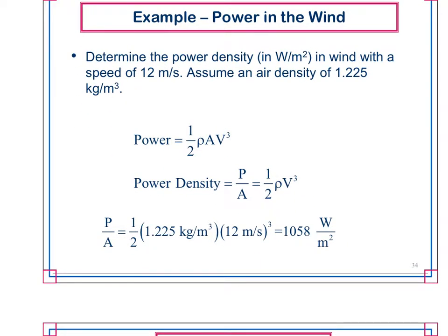So let's take a look at what the question. Does changing the number of blades on a turbine, it seems like it wouldn't change anything in that equation. Does it change the efficiency? Very good question. So adding or decreasing, because you can go down, right? Because we're typically seeing 3. Increasing or decreasing the number of blades does affect efficiency, but it's not a one-for-one relationship.